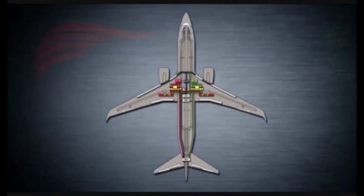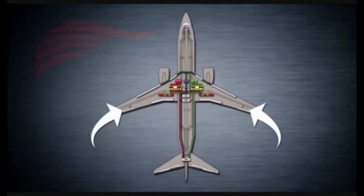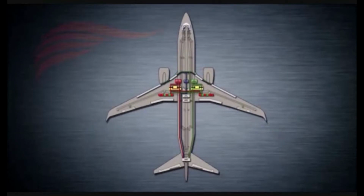Ailerons are movable surfaces on both wing outboard trailing edges that control the flight attitude of the aircraft about the longitudinal axis, more commonly known as roll. The ailerons are coupled so that when one of them moves down, the other moves up. There are three ways of achieving roll control on the 737NG. Manually, by moving either control wheel, automatically, by autopilot input to move control wheels with actuators, or through flight spoilers.